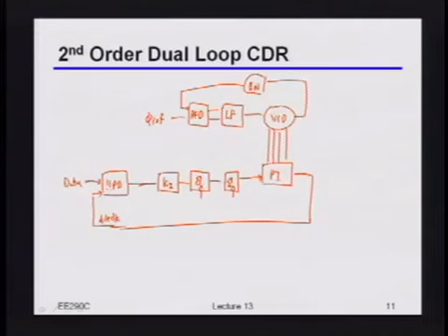Yeah, I have a feed-forward path, and in particular, when you say feed-forward path, where does that get added in? From the output of the first accumulator? Yeah, exactly. So by direct analogy with a normal PLL, I'll have something that's usually called the proportional gain. And I'll have that jump around the integral section, and then feed that proportional gain into the last accumulator. Okay?